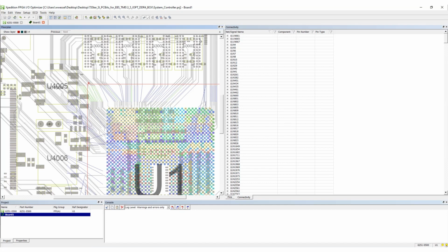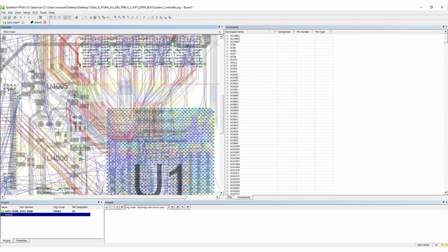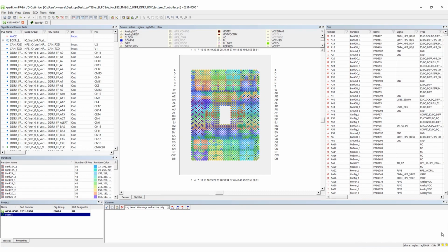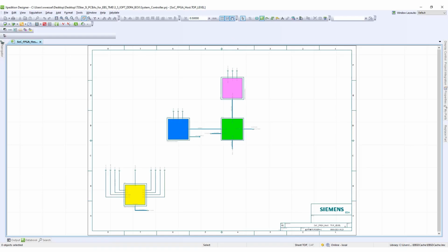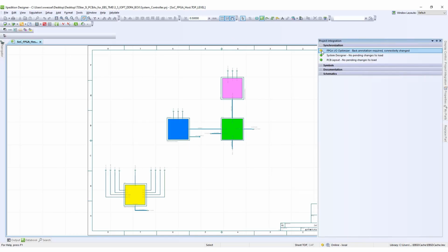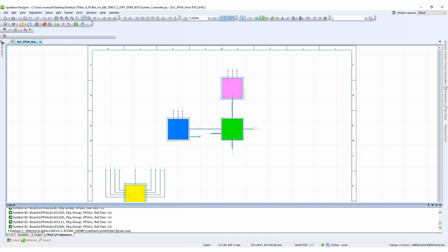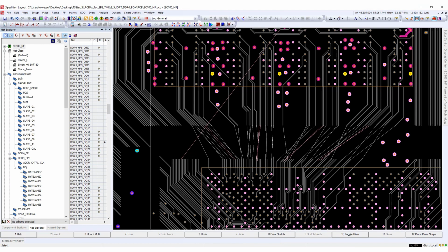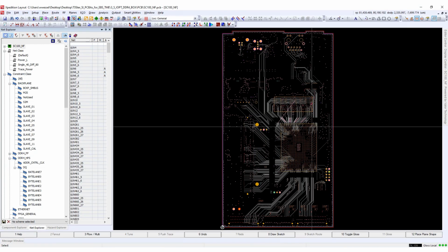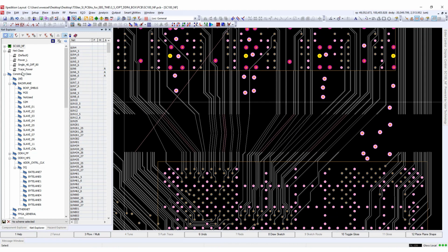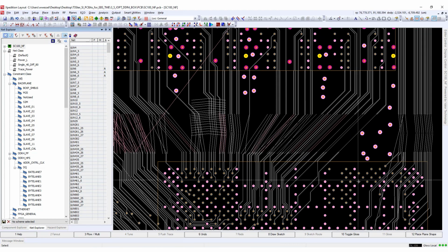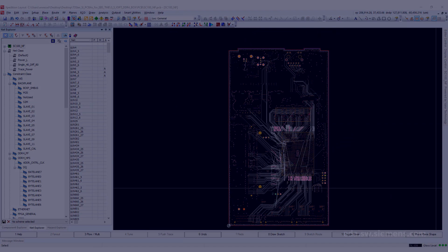The engineering change order process does not only write back data to the PCB domain. It fully supports a bidirectional exchange of native file formats from FPGA vendors like Intel, Xilinx, Lattice, and Microsemi. In our case, we are using a VHDL signal source and a QSF constraint file for the pin location. Zach can now use Xpedition routing technology to finish this optimized set of signals.